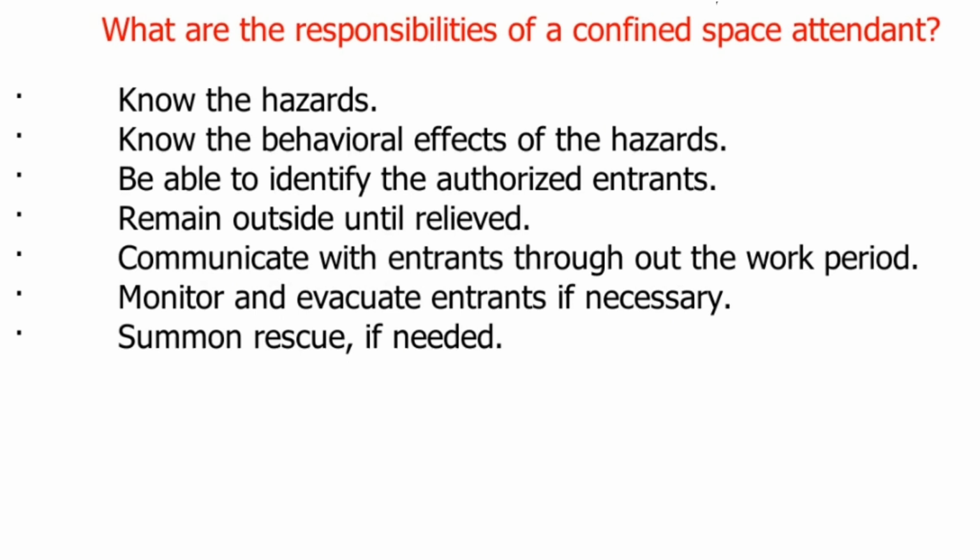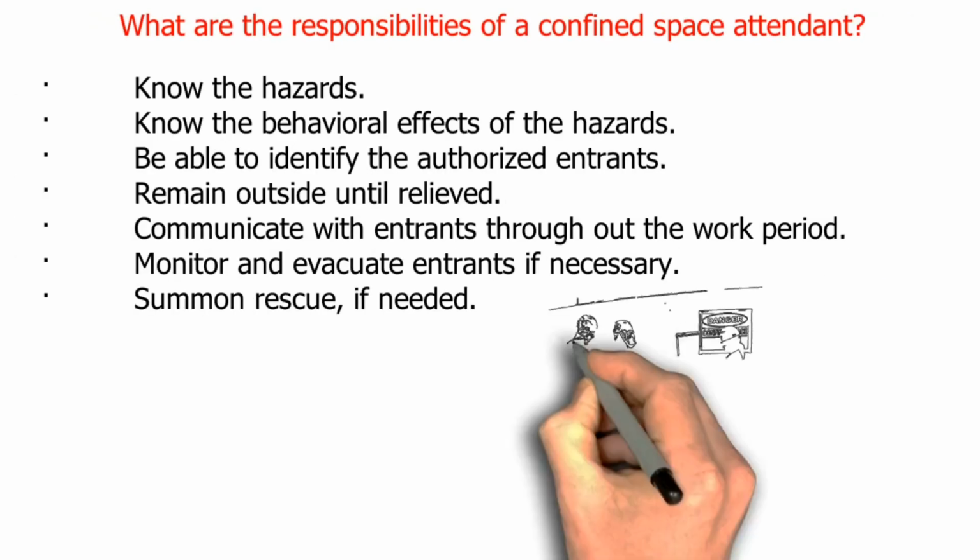What are the responsibilities of a confined space attendant? Know the hazards. Know the behavioral effects of the hazards. Be able to identify the authorized entrant. Remain outside until relieved. Communicate with entrants throughout the work period. Monitor and evacuate entrants if necessary. Summon rescue, if needed.